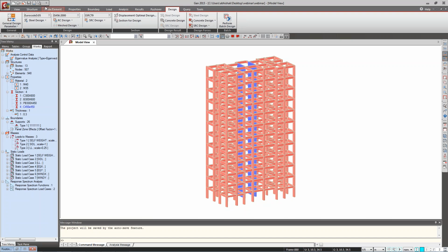So generally in the structure, you just go and say check slash duplicate element. Automatically the program itself cross-checks, and it automatically detects whether it is a duplicate or not. If a member is duplicated at the time of loading, it gives the error that the member is duplicated. And now, you are asking about the meshing.